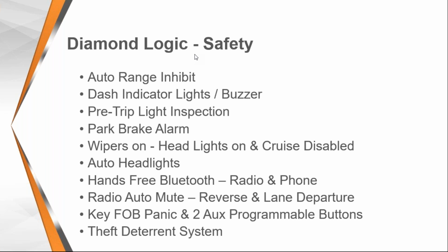Theft deterrent, if a truck is ordered with that, there's 6 switches in the dash, and the vehicle will start and run and idle just fine. If someone tries to release the park brake, this code, if not entered, it will die within so many seconds. So if they enter the code before they release the park brake, then if it's the correct code, they can drive off.